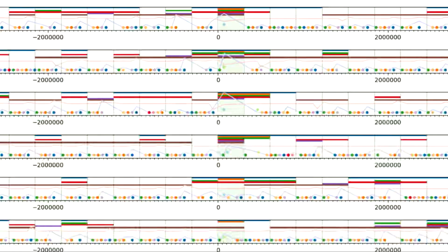And what this giant mess is actually showing you is, for example, how do I explain this? At every gray vertical line, we were sending a new card information message. Only, and I know from the way that I've set up the controller, only one of the facility codes is valid. And we send that valid facility code when it's the green shaded box. So looking left to right at the top, you've got 1, 2, 3, 4, 5, 6, 7, 8 invalid cards, then you've got a valid card, and then 8 more invalid cards.